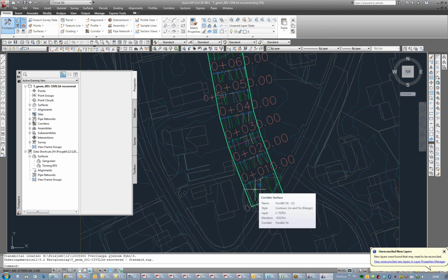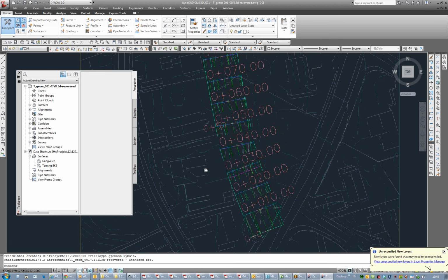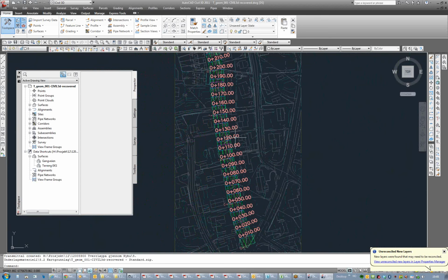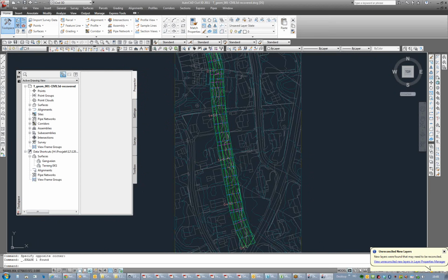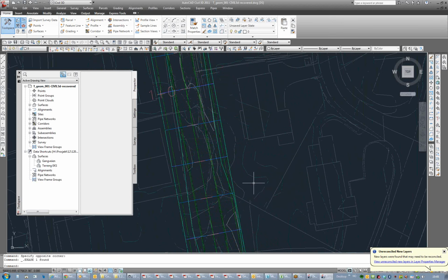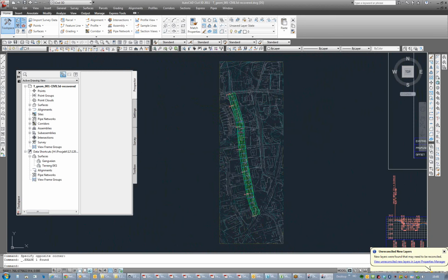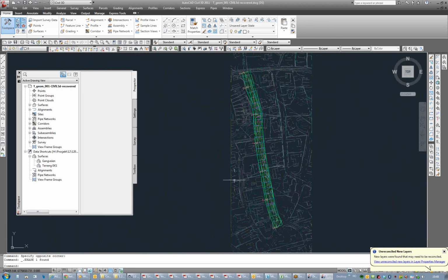Yeah. The walls, you can do that with a feature line. Point to point to point. Just make sure that with the property lines, because I have the property line corners. Yeah, you can do the same thing with the property lines, and with the wall you would just create a stepped offset for your toe of wall, bottom of wall, and top of wall.